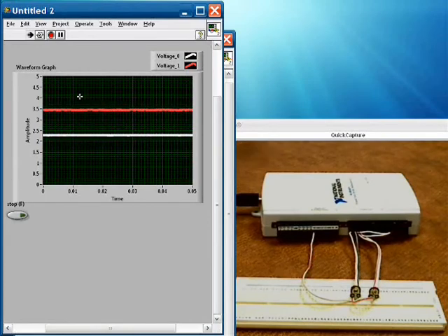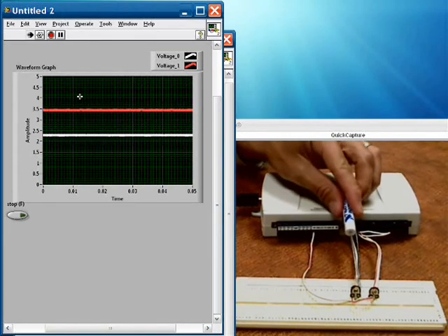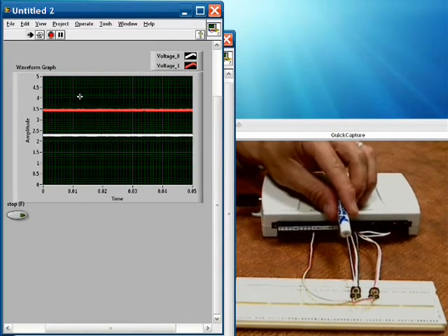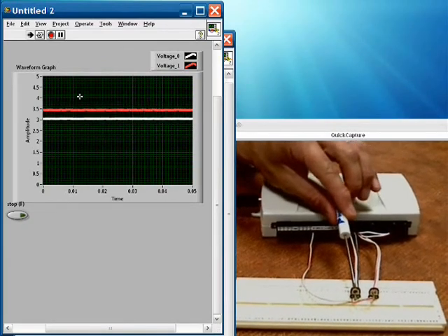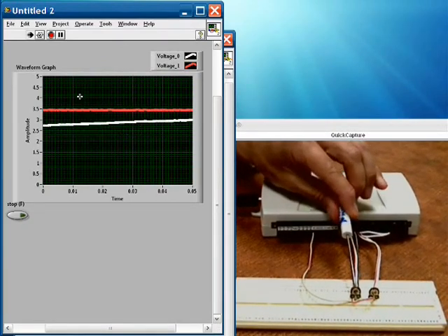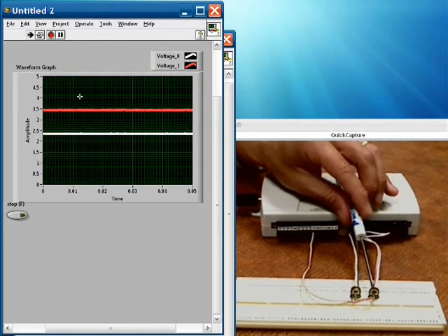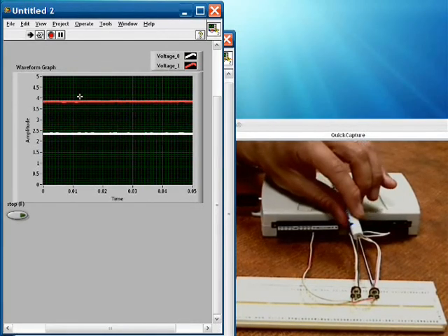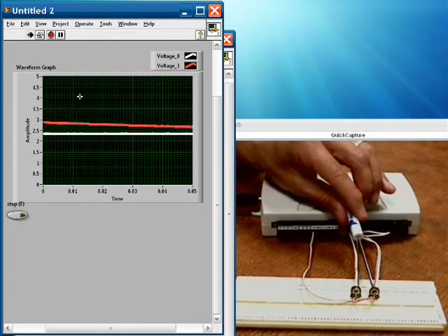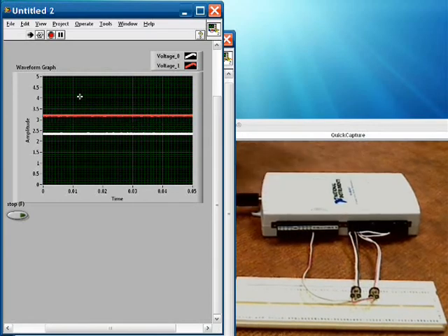analog input. Now I'm going to take the screwdriver and insert it into the potentiometer here, and when I turn this, you're actually going to see that the waveform moves on the screen there. And that's an independent channel from my second channel, my AI2 channel. And when I put this in here, you'll see that they run independently of each other. So what you're seeing are snapshots of 5,000 samples at a time, and these are being acquired at 100,000 samples per second per channel. So this is how you would set up and do analog input acquisition with the USB 6211.